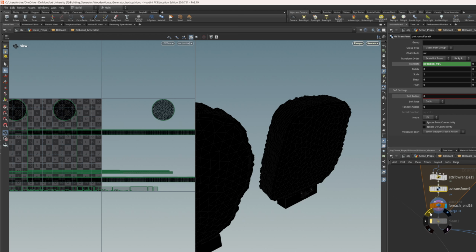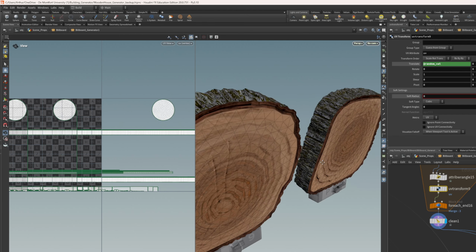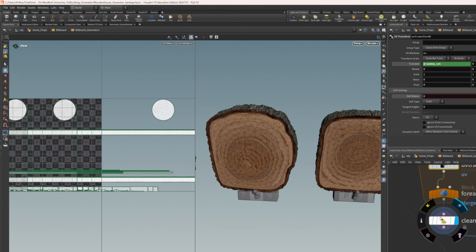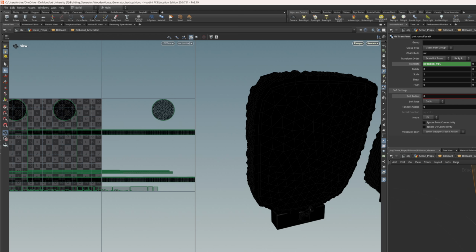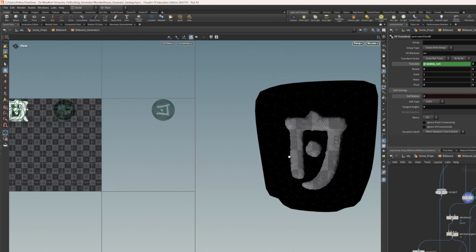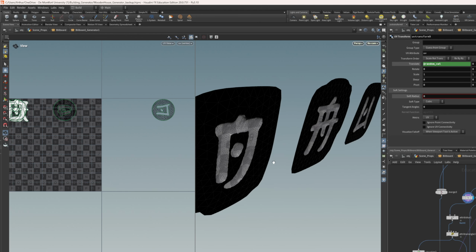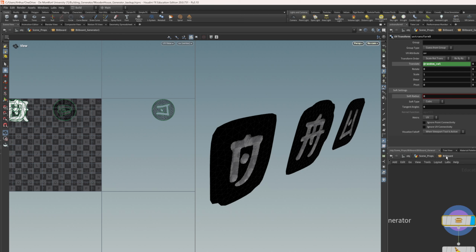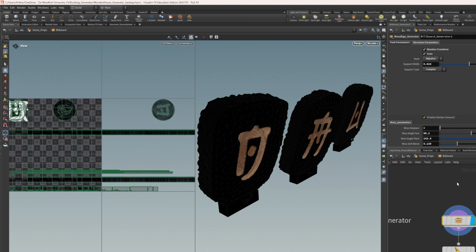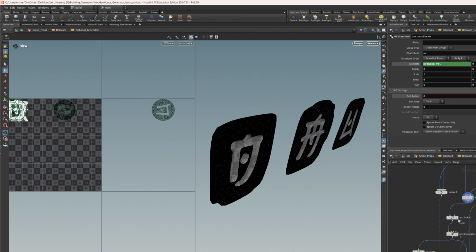So then we've got variation in the UVs, which I think is really clean. Okay, so we can stick this on in case we want to look at it without the CD values, but we'll just leave it off for now because we are focusing more on the vertex colors now. So let's get down to Boolean. So the Boolean now cuts the letter out from the front face. Now I think it's probably a good time to put vertex colors on. We're gonna let that cook.